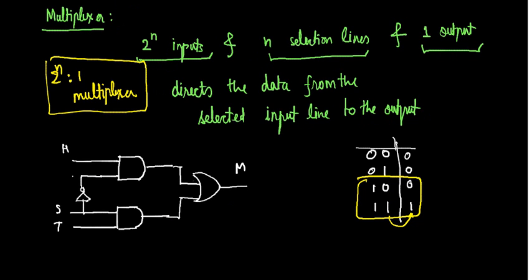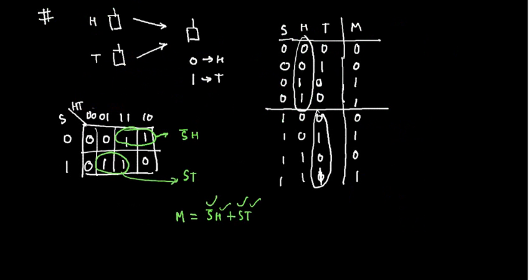So selection lines are simply there to activate. Now see the previous expression. Here the selection line is simply activating Hindi or Telugu. When it is activating Hindi, it will transfer data from Hindi. Here it is selecting or activating Telugu. So the selection lines are not inputs, but the activators or activating variables, so that the data can be received from only one person. It doesn't matter if the other is transmitting. Don't confuse the selection lines with the inputs. They are the selection variables or activating variables. Yes.